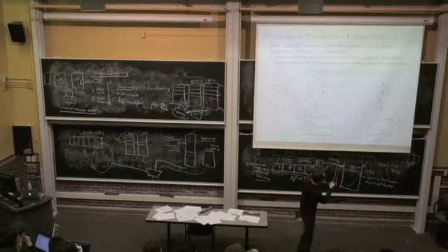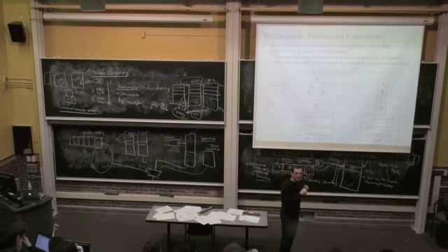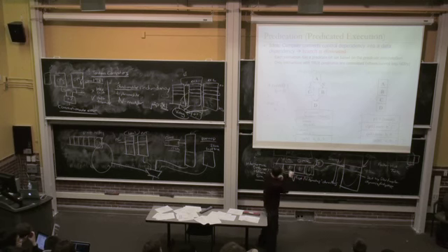So the idea is this predicate is really a data dependency now, right? So you're really not branching in the code, but you need to satisfy the data dependencies. So here, there was no data dependency between P1 and the move instructions. Now the move instruction is really dependent on P1.